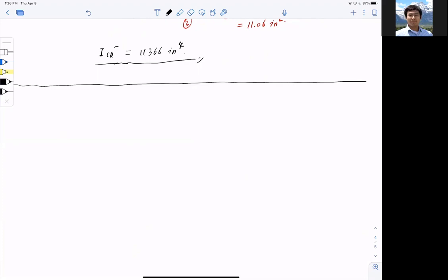So let me do the drawing in a simplified manner. This is my column, and that's another column here. And this is my beam here in the middle. All right. And I say that, look, the moment follows this nice diagram here, and this is MA positive, and this is MA negative. And I want to find out, for example, here, my effective moment of inertia at midspan. So how do I do that?